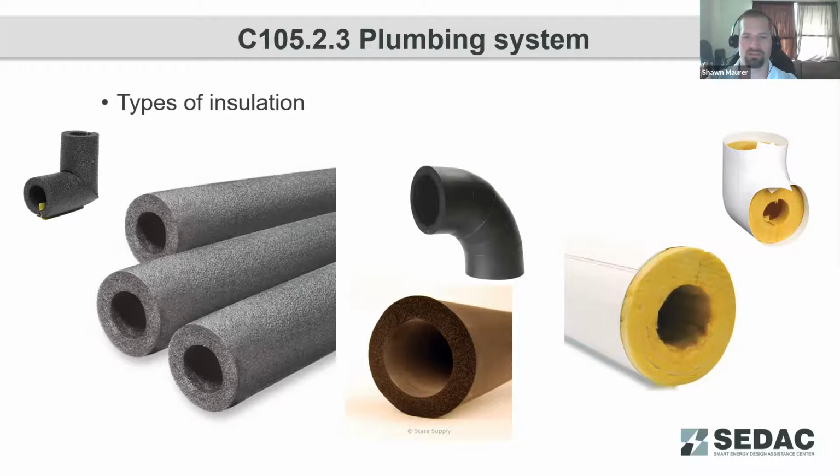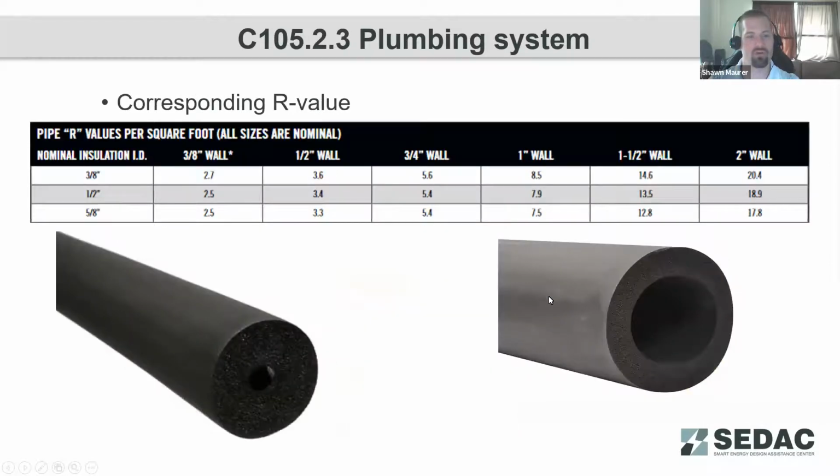As we go through buildings and do retro commissioning projects, typically where we see insulation damages on the outside of bends, and then in some instances where people use the piping as ladders and try to climb up to higher spaces, and they'll wear down that insulation. But making sure that those wraps are properly installed where you're not compressing that insulation, maintaining that full thickness for that full R value is important for the overall performance of the system.